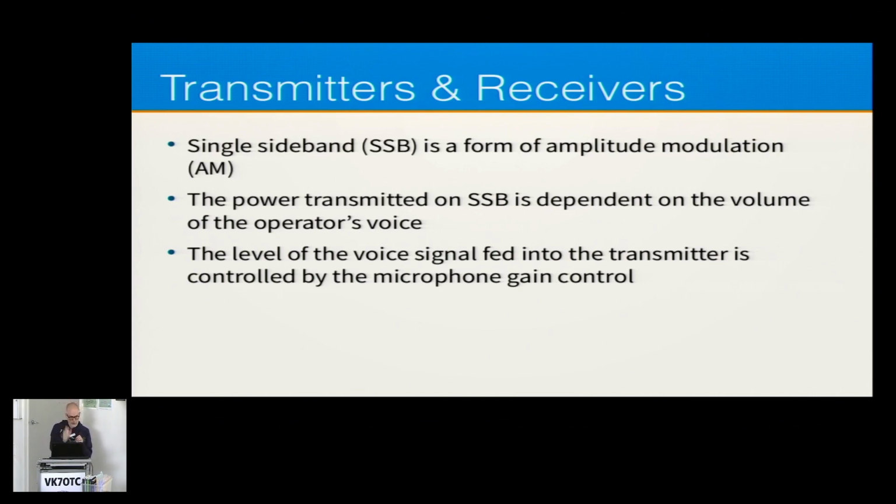So it's a very efficient mode of transmitting information because it's only there when you talk, when there's something modulating it. It's also a very power efficient mode because you're only transmitting power when you're talking. When you're not talking, there's no power being transmitted. So yeah, it's single sideband. But the thing you need to know as a foundation license candidate is it is a form of amplitude modulation because the size of that signal goes up and down with your voice.